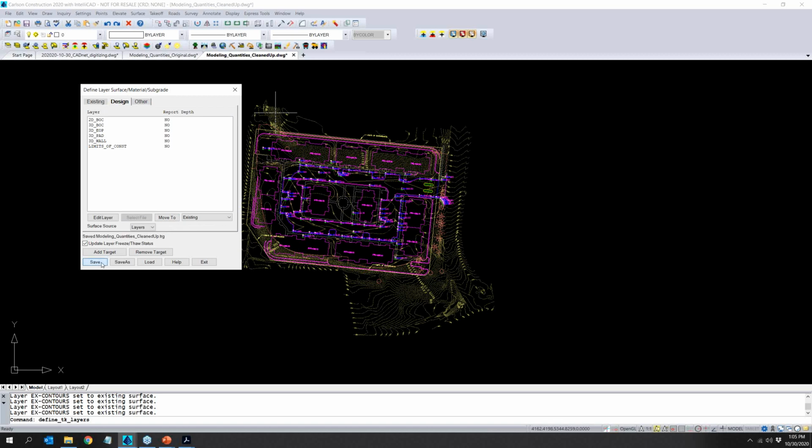It's important to save here because you're saving all this data into this TRG. It's a target file. I haven't really done anything in this drawing; this is where the changes are being saved. So this is important. If you save or archive or have to send this to somebody else, you want to send the drawing plus this target file. Are there any questions on this?